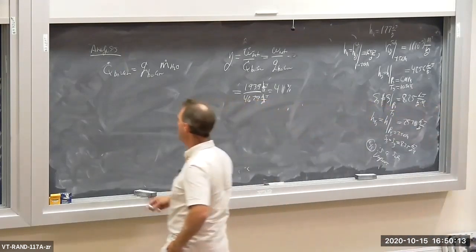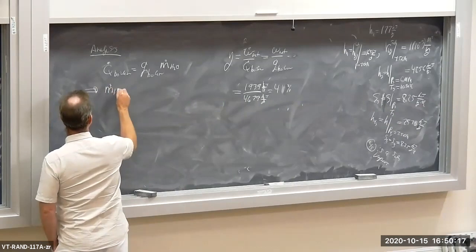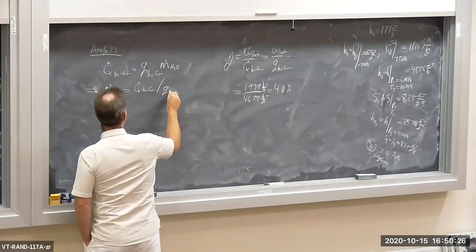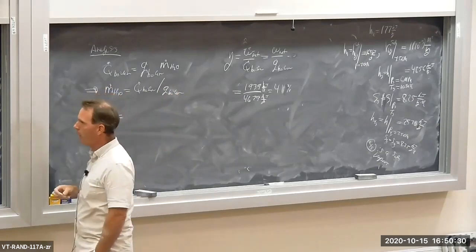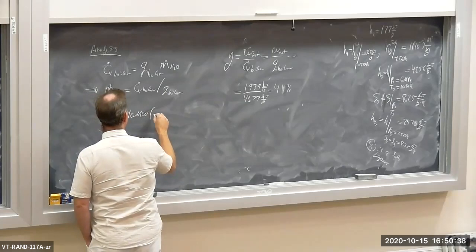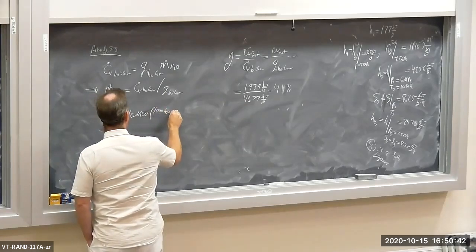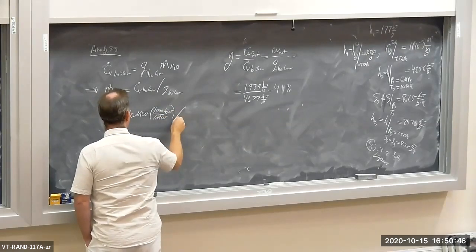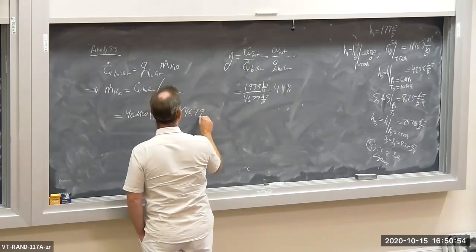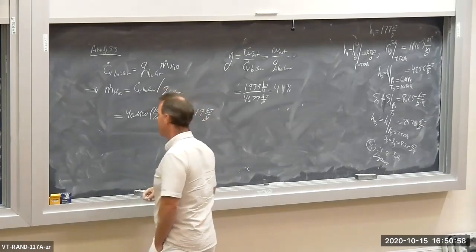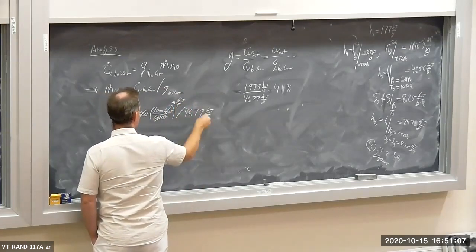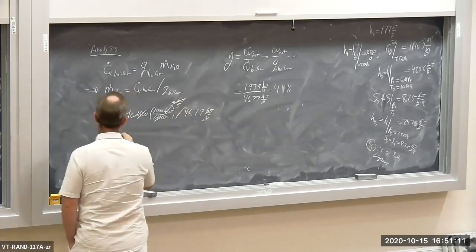So therefore, m dot H2O, the mass flow rate of the H2O around my cycle, is equal to Q dot boiler divided by q boiler. Q dot boiler is 40 megawatts. I'm going to convert that into kilowatts, so that's 1,000 kilowatts per megawatt, and divide by the specific heat addition of the boiler, 4679 kilojoules per kilogram. The megawatts cancel, a kilowatt is a kilojoule per second, the kilojoules cancel out, and I get kilograms per second, which is exactly what I want.